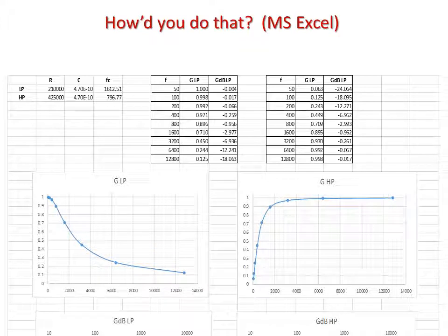So again, this is another more detailed part of how we get our low pass and our high pass frequency. With this, you can plug in values if you have a calculator essentially set up for this. You can plug in resistor values to be able to tune your circuit to get that perfect combination of resistor and capacitor to get the end frequency.